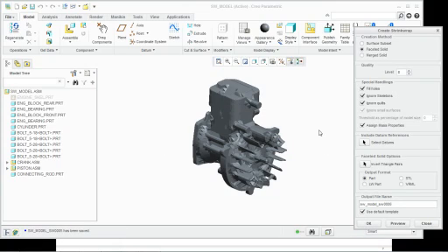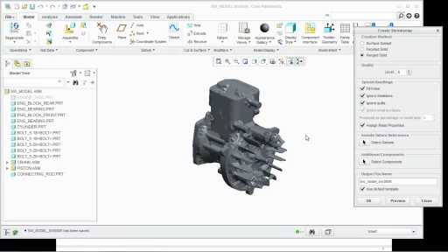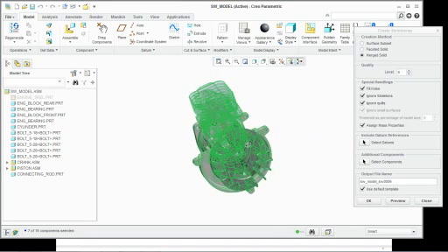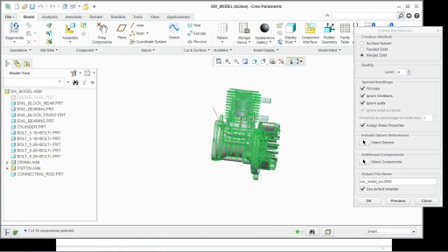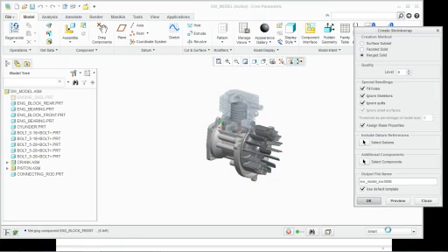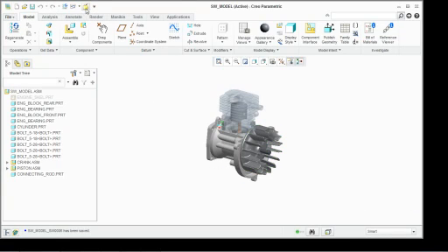and let that generate. And then we're going to create a third one, merge solid. And this one we're going to crank the level back down to 6. Click preview, and notice it's going to give you pretty much everything you had before. It's kept 7 of the 16 components. So we're going to click OK, and we're going to click close, and I'm going to open another file here.